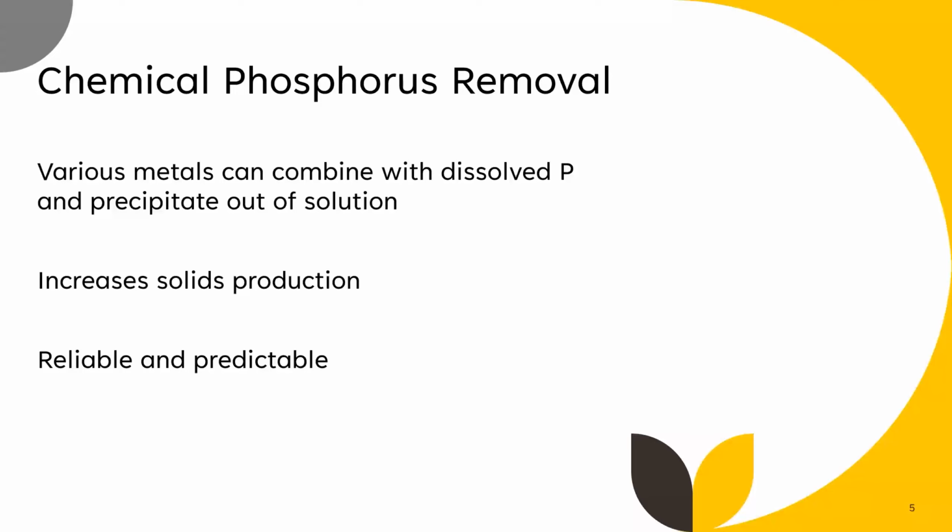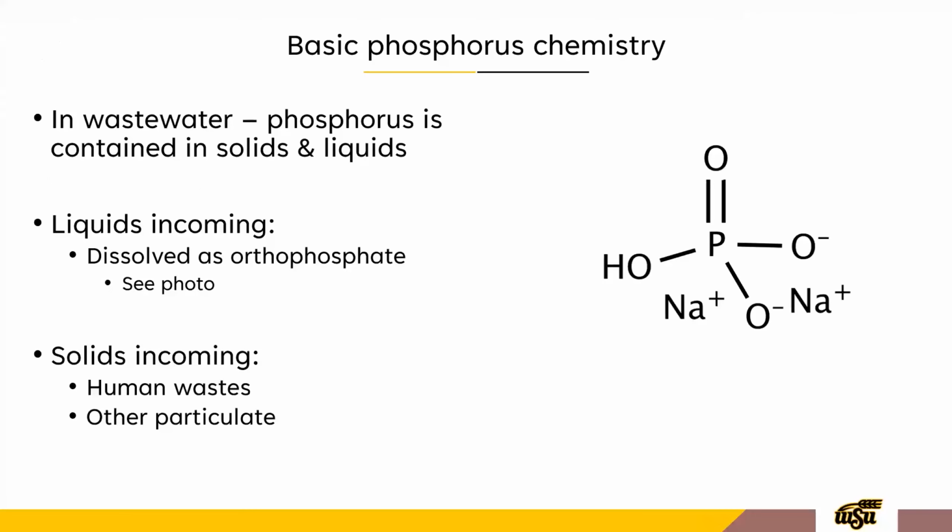There's no toxicity that is going to come about with chemical phosphorus removal. You're not going to run out of BOD or have some other kind of biological upset occur, but it's also pretty expensive, which is why KDHE and Grant and I both tend to focus on biological phosphorus removal if possible.